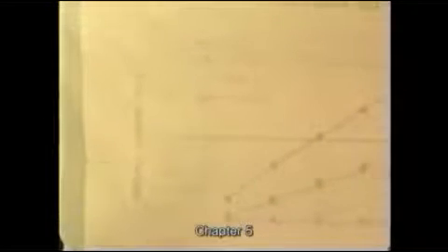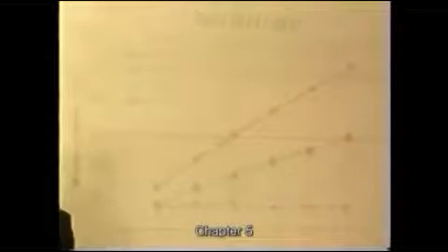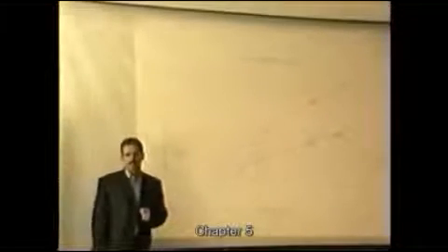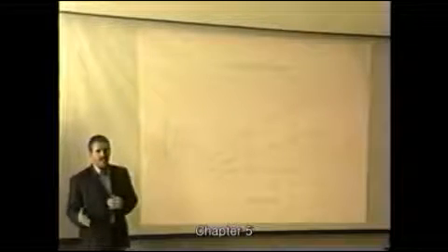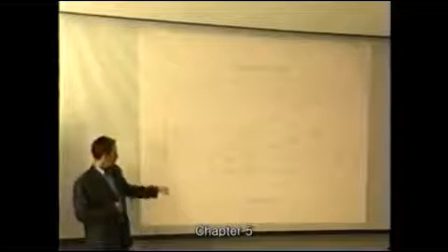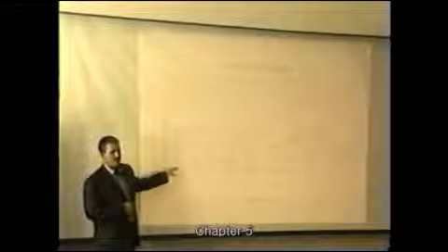So you can draw up these curves, and this was done for a reactor that is supposed to treat 20 megaliters a day, which is 20,000 tons, and then operated at certain mixed liquor concentrations. The straight line is the actual basin size. Okay, it's less than 2,000 cubic meters, less than 2 megaliters. So the residence time in this basin is approximately 2 hours.